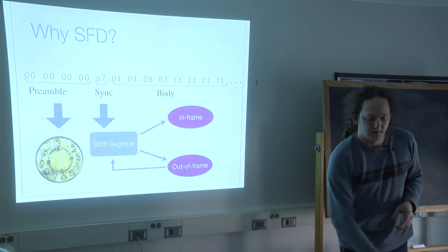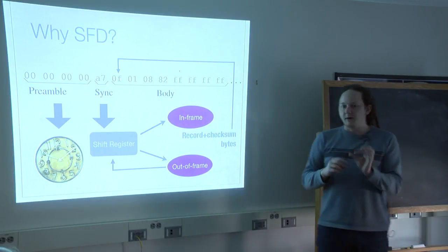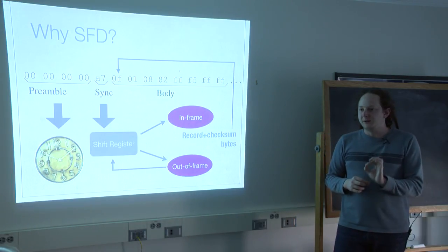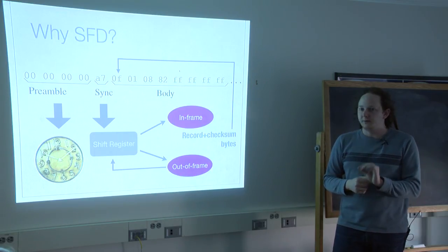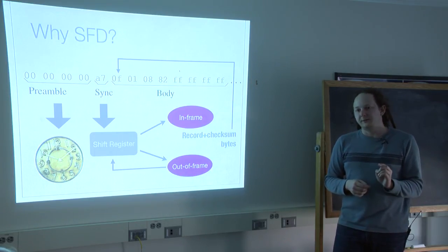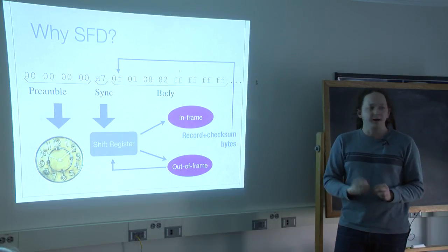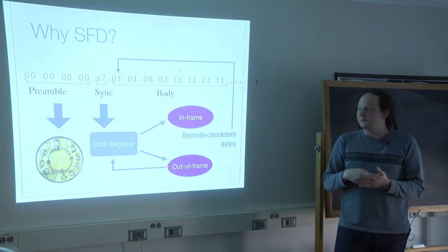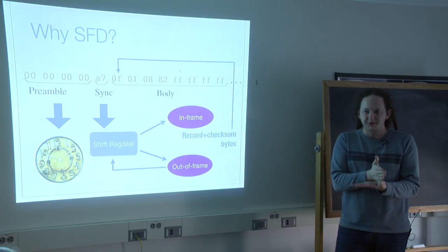It's a common bug in updating the microcontroller on one of these boards that the packets begin to become corrupted. And the reason why is that the older chips would default to 3 megahertz, and the new chips default to 16 megahertz, which means that the new microcontrollers can read the packet out of the buffer faster than the buffer is populated by the radio. So during that time, the copy routine passes the end of the packet.